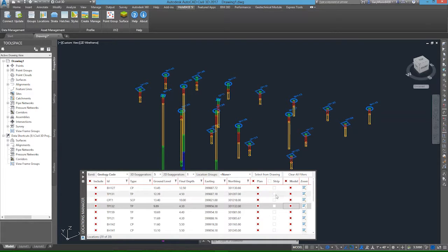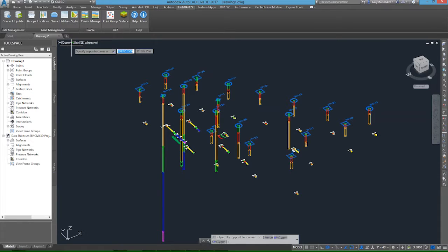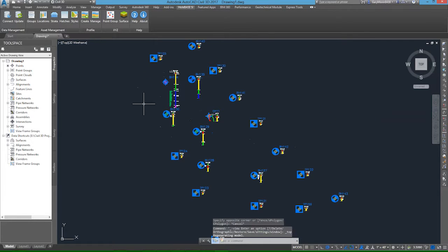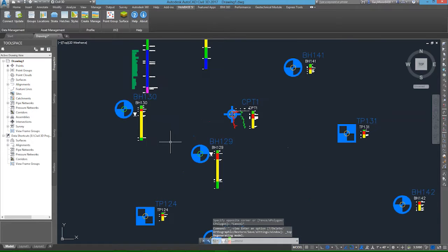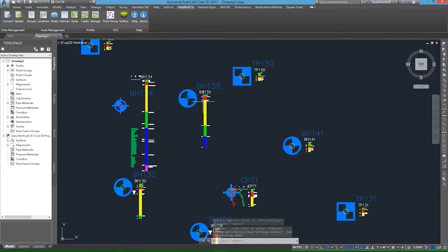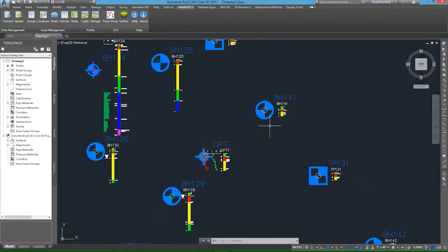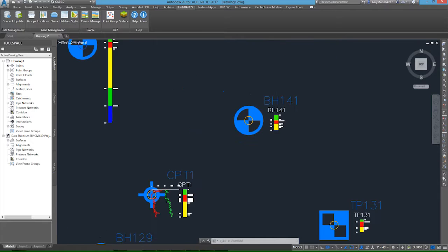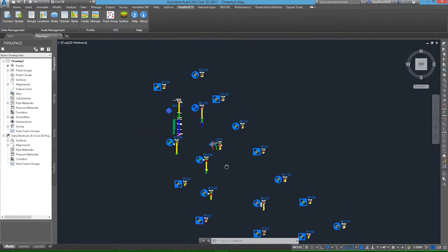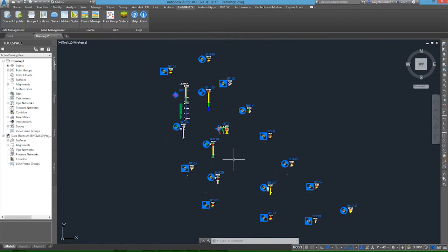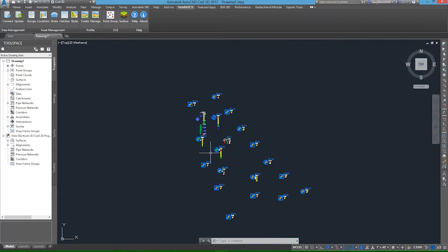The other thing we can do is click on this icon here called strips. Let me just come out of here and go to my top view. We can also look at the boreholes and the log strips on plan. It's a great way of quickly looking at and understanding what geology you've got across the site, and looking at the geology codes to see what they are around the site. It's quick and easy to pull the information in that way as well.